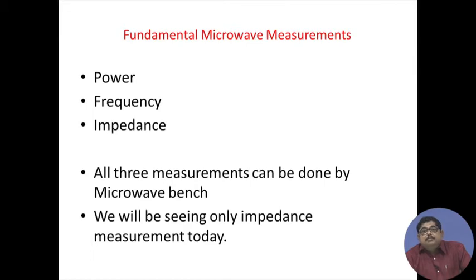because in both low frequency and high frequency, impedance characterizes the network. A network does not get characterized by its voltage excitation or its current response, but by the ratio of those.